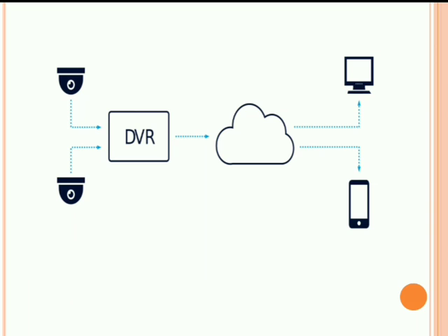The video management software, VMS, records, stores and analyzes the video feed. The software is often self-learning software using machine learning algorithms that utilize functionality like motion detection, face recognition, people counting, etc. The monitors can be passively or actively monitored by software or by people respectively. The CCTV network can and should itself be monitored. This is how the CCTV system works.